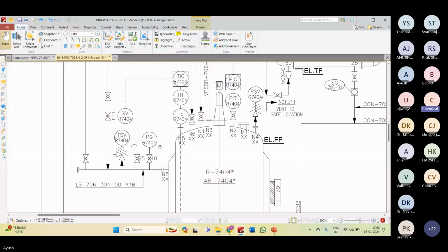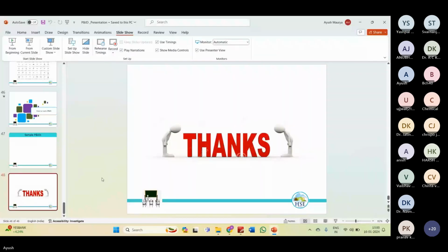One more question is: what necessary information is shown on the material balance and energy balance sheet? Yeah. So basically, the first thing is quantity, their purity, and specification in general. Then in energy balance, normally we give the temperature and pressure also along with the flow. In material balance also, it is better to share these things. So these are the basic requirements: specification, temperature and pressure, and some other property-specific information, like corrosive material or radioactive material, that we can also mention in the material balance.